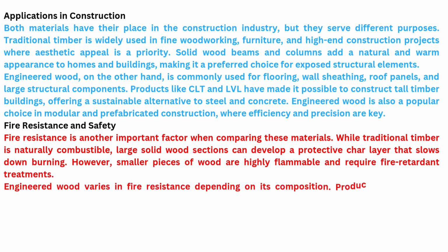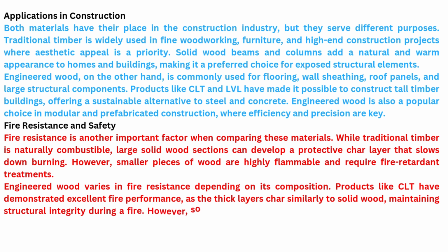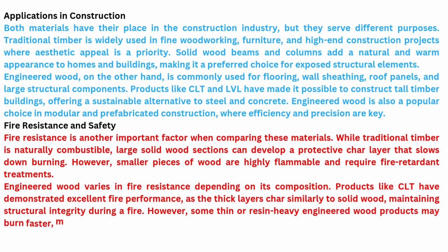Engineered wood varies in fire resistance depending on its composition. Products like CLT have demonstrated excellent fire performance, as the thick layers char similarly to solid wood, maintaining structural integrity during a fire. However, some thin or resin-heavy engineered wood products may burn faster, making fire-resistant coatings essential for safety compliance. Choosing the right material for your project.